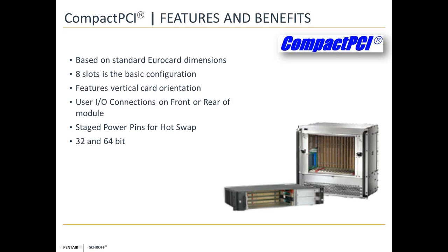There are, however, some disadvantages, and those include slow data transfer rates. It only goes up to about 133 megabytes per second. And like VME and VME64, it has a parallel bus structure, so it is limited. It only supports one single protocol, which of course is PCI, and it only has single master capabilities. And of course, it is limited to 8 slots, as I mentioned, without bridges. Bridges will take you up to about 21 slots.